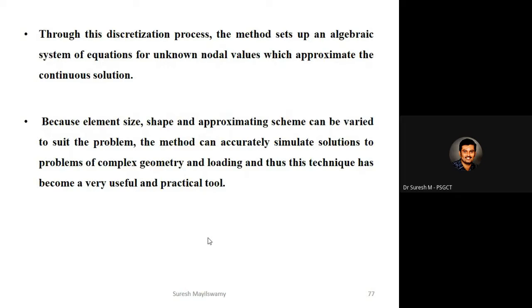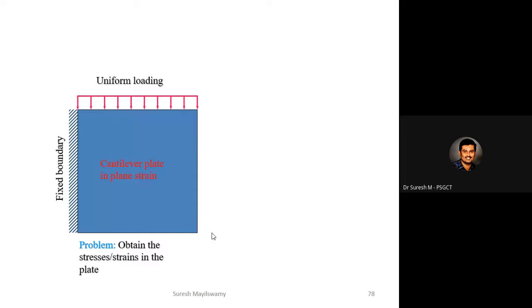Through this discretization process, the method sets up an algebraic system of equations for unknown nodal values which approximate the continuous solution. Based on the element size, shape, and approximating scheme can be varied to suit the problems. The method can accurately simulate solutions of problems of complex geometry and loading, and thus this technique has become a very useful and practical tool. So this is more widely used.